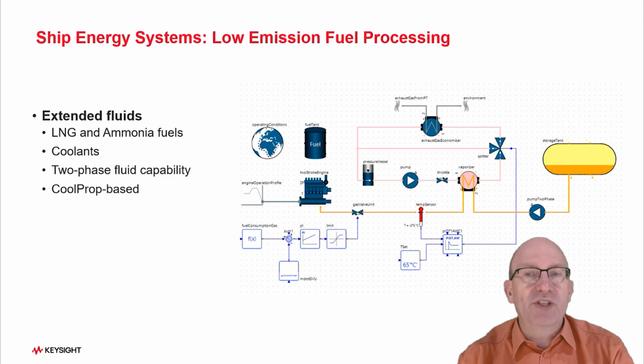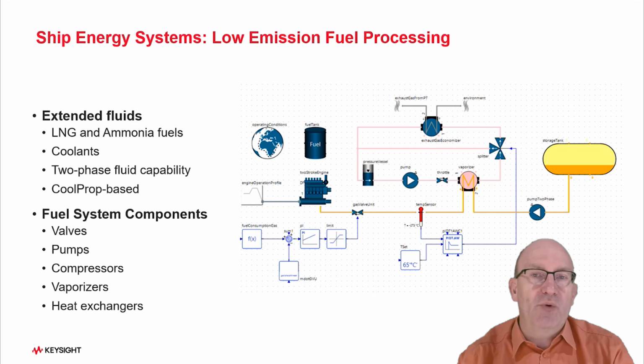So we have new fluids, we have additional coolants which are used in these circumstances. We have introduced two-phase fluids into ship energy system modeling in order to address this two-phase scenario, the change from liquid to gas state, and all this I mentioned before. CoolProp also here, we use CoolProp Fluid in order to implement this for the ship energy systems library.